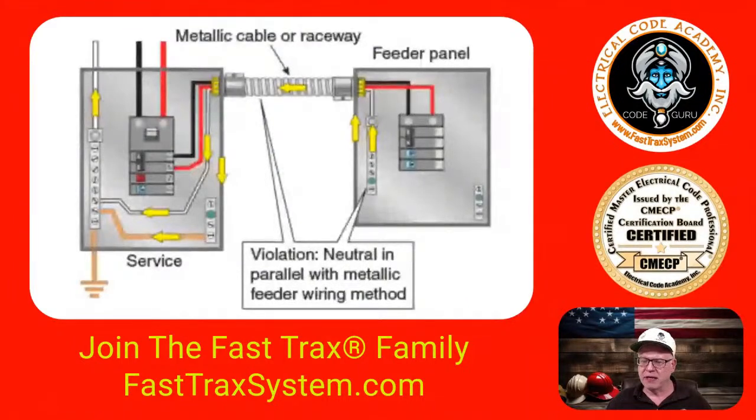So right here, whether we can just remove this screw or not and make this compliant really gets into a deeper discussion on what type of wiring method we're using. And in this illustration right here, it's evident this is not going to be MC cable. And it's evident that this overcurrent device, whether you want to argue that or not, we're not going to feed a panel like this with a 20 amp circuit.